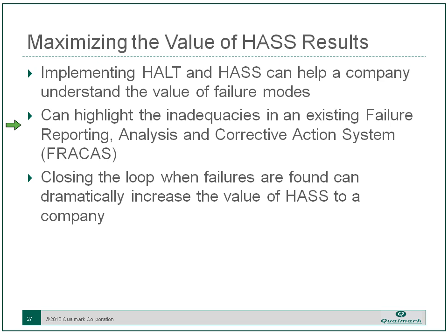The problem is that often FRACAS is not implemented as fully as it can be, because you'll have in your field service depot a barrel where the bad units go in, and nobody ever digs into them to understand what the failure modes were. And in production, if a unit fails and they take a pass at fixing it and it fails again, then it goes in the trash can.